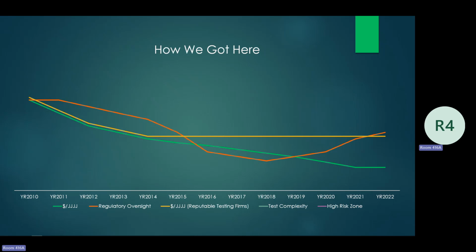We as stationary RICE testers could say, look, we have done thousands, tens of thousands of tests over the last decade with FTIR analyzers. We can show you that we don't need to go to this level of spike recoveries for these compounds on these engines. We have proved that the sample can transmit or carry these compounds from the exhaust stream down to the analyzer. There's no other test method that requires this level of dynamic spiking anyhow for these compounds.